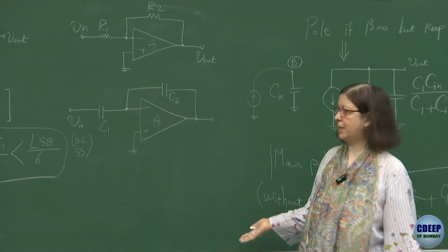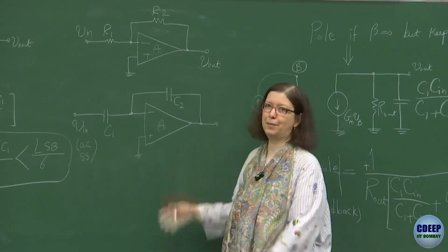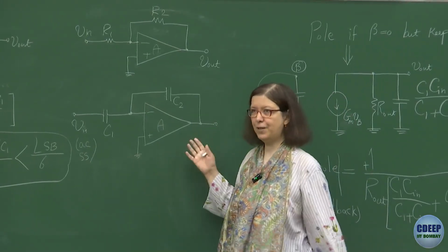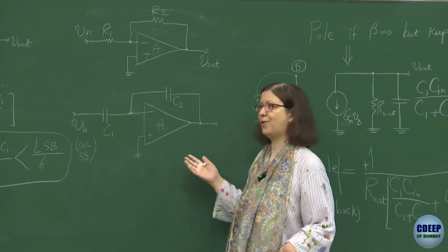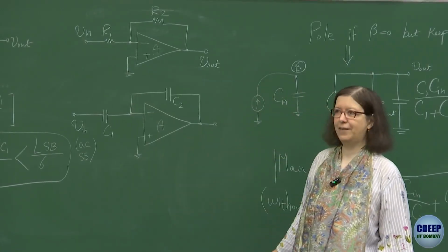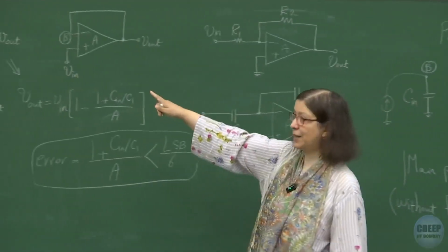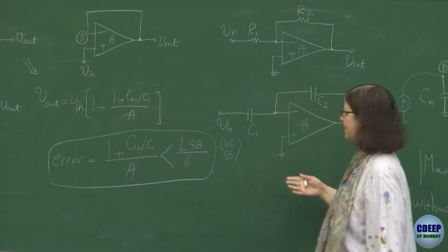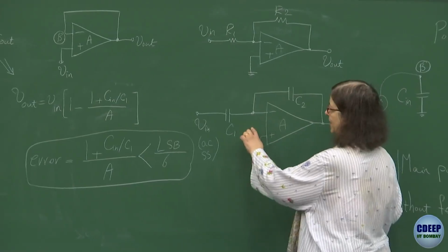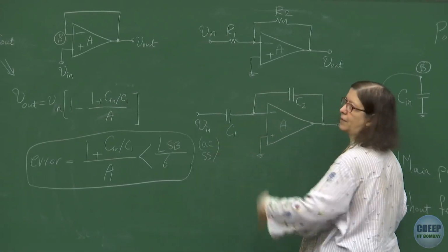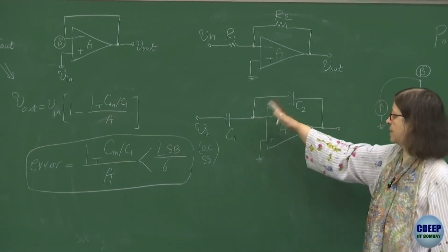We replace them, but the only difference is that you have to switch these capacitors. So therefore, it's a switched capacitor amplifier. We move from that single capacitor case to the double capacitor case, and that is what I was telling you. This Cin will also see a C1 on the left, and a C2 on the right.